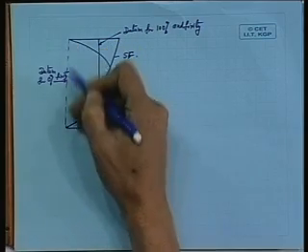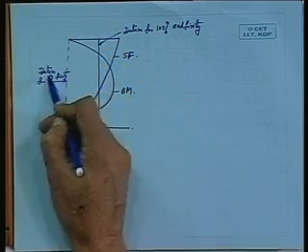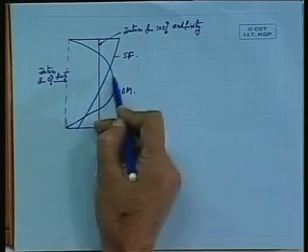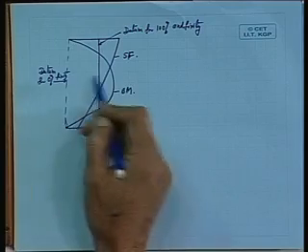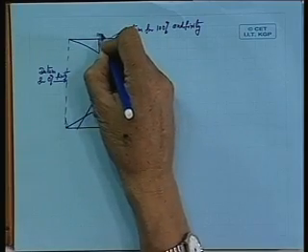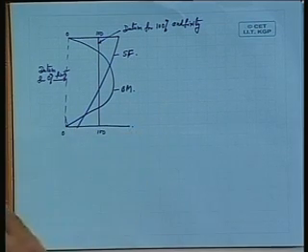So, just making the two bending moments 0, if I join this straight line and consider this to be the datum, then with respect to this line I can say that this is for the 0 fixity bending moment curve. So, you have 100 here, you have 0 here, you have 0%, you have 100%.